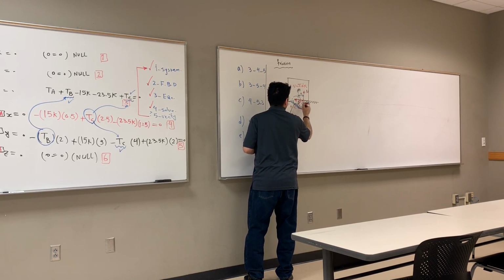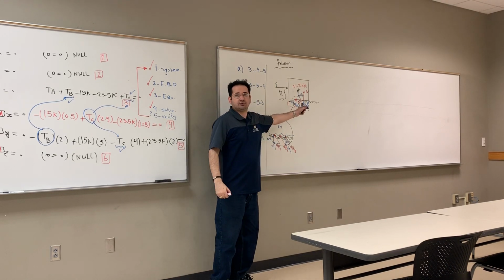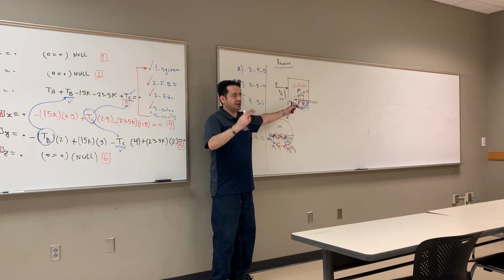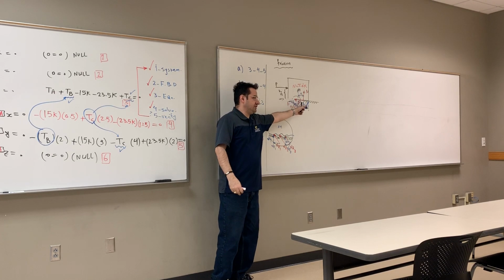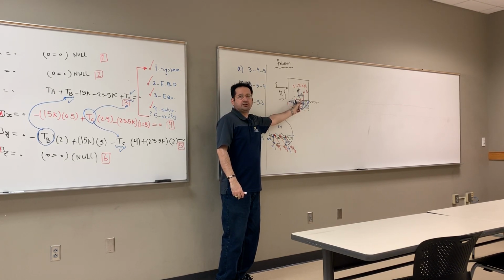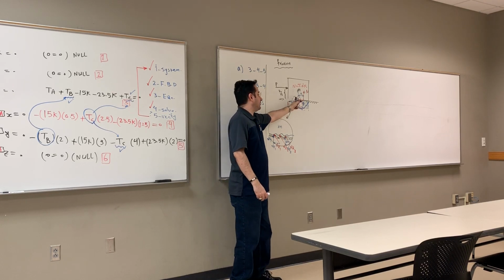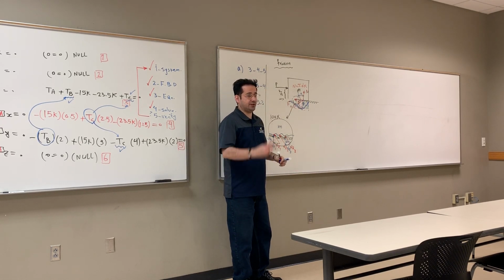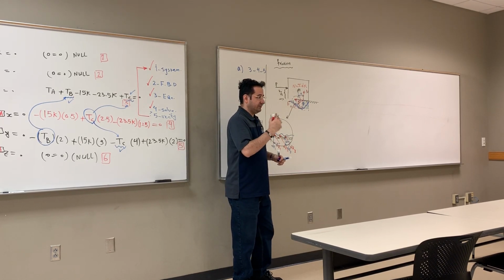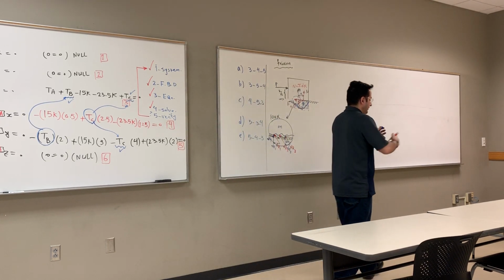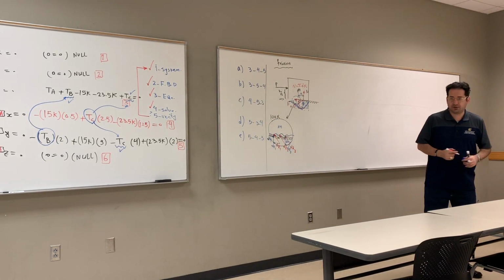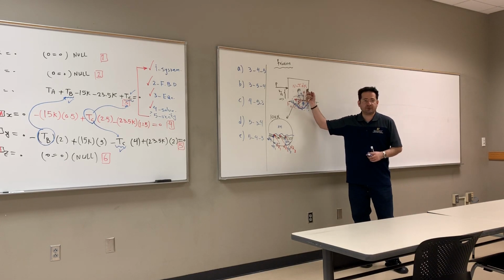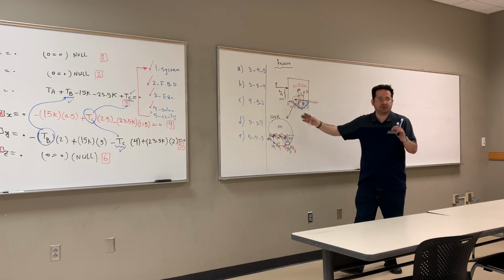And F. So that's what you get. For every friction force, you get 3 unknowns: a location that we don't know, a component opposite to the direction of motion, call it F, and a component normal to the direction of motion, which we call N. So we get 3 per friction force in the system. If I have 3 objects, every one of them gets a different friction, F, N, and X, different, right?